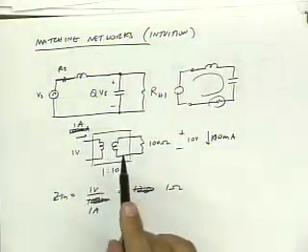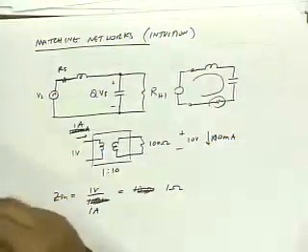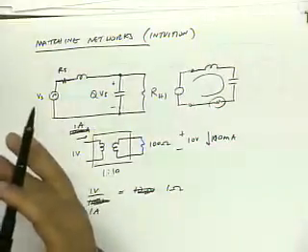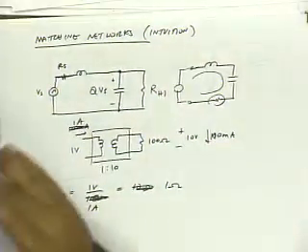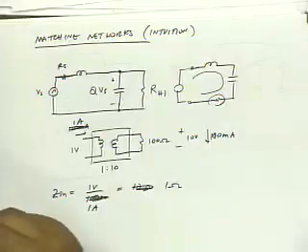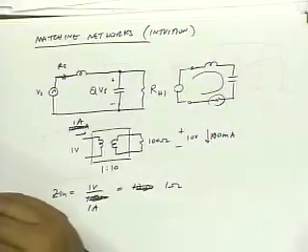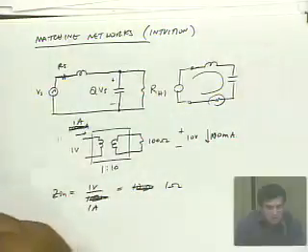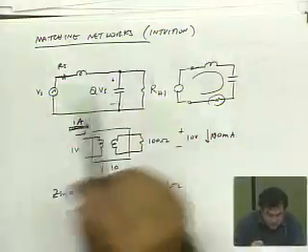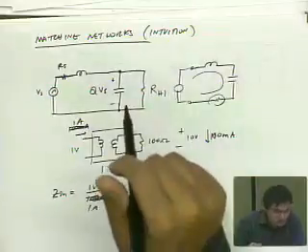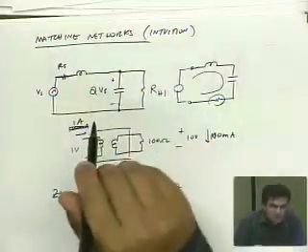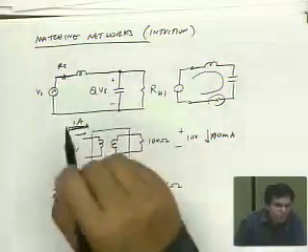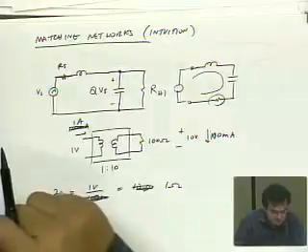And intuitively, though, you would say, well, if it boosts it by Q, then it should go up like Q squared, right? So if you didn't do any calculations and you said, I have a circuit that can boost the voltage by a factor of Q, therefore it should be able to boost the impedance by Q squared, or vice versa. That's pretty much what we found when we did the exact analysis. The only difference was it was 1 plus Q squared. And the reason is that we don't exactly have series and parallel circuits. They're slightly different. When you transform them, that extra factor of 1 comes into play.